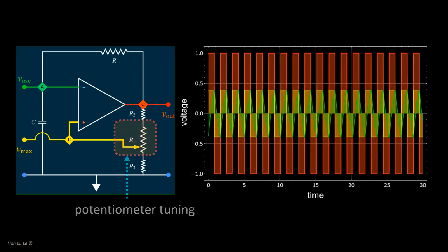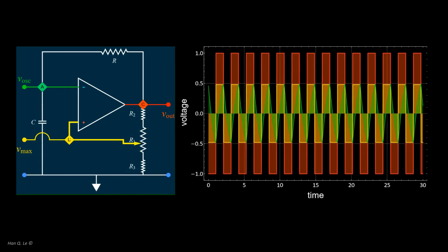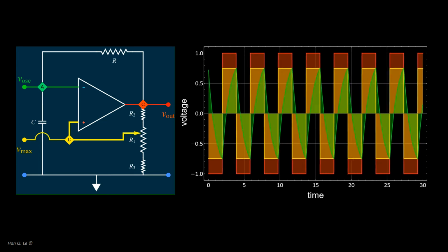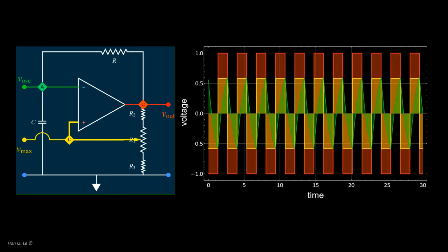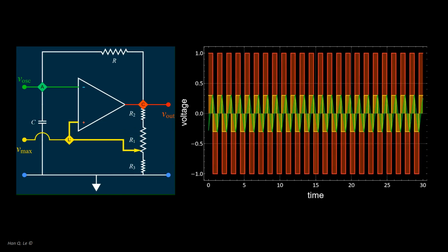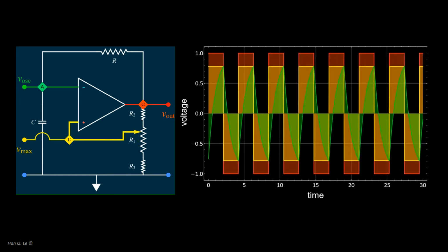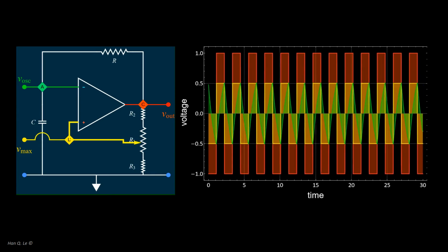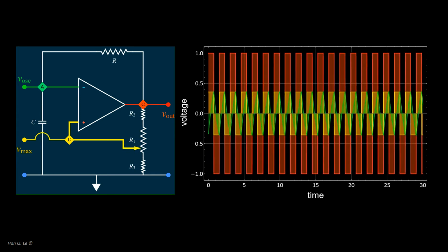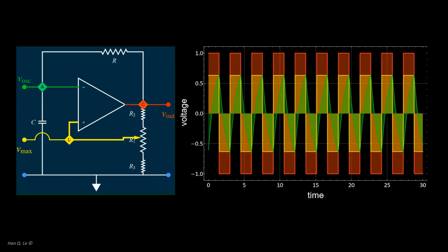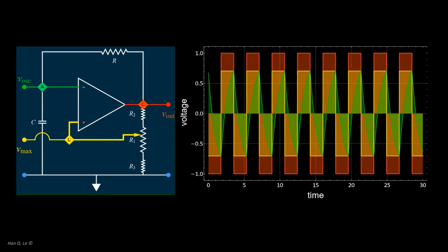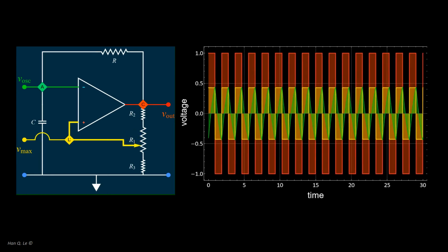The lower the ratio, the faster VA, that is, the voltage of the inverting terminal, can catch up with VB, hence it results in higher oscillation frequency. With a potentiometer for the feedback, one can control both the amplitude of VA and the frequency. However, you have only one potentiometer, and the circuit need not be more complex for this particular task.